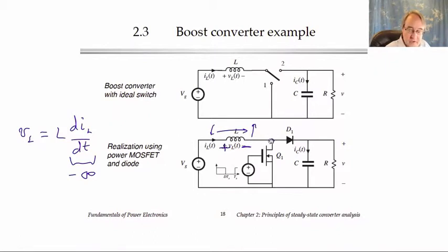So this node here, where the MOSFET is connected, will head to a large positive voltage from the voltage developed in the inductor. It heads towards plus infinity, but long before it gets there, it forward biases the diode. In fact, when this voltage rises above the output voltage, the diode will turn on and clamp this voltage to the output.